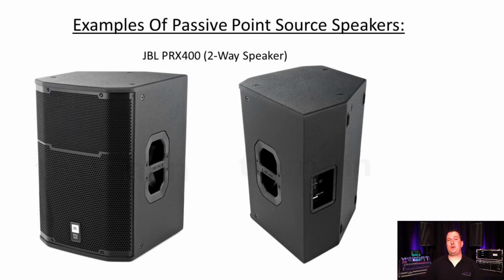Okay, so let's have a look at some speaker examples. First, we have the JBL PRX 400 two-way or full-range speaker system with a high and low frequency driver that covers the frequency range of 50 Hz to 20 kHz. This specific model is a passive speaker and will require an external amplifier to work with the needed Speakon or NL4 connectors on the back panel. They are available in 12-inch and 15-inch sizes.